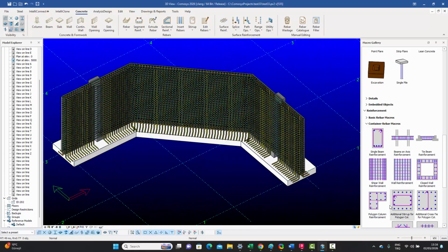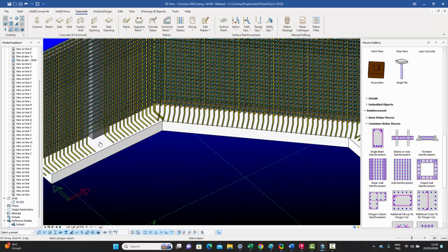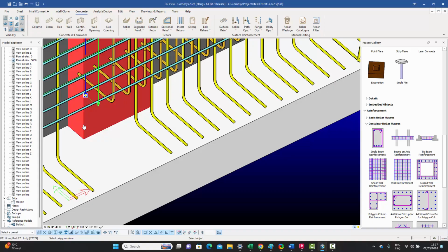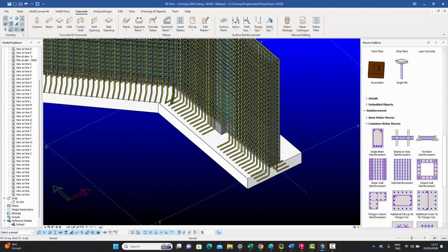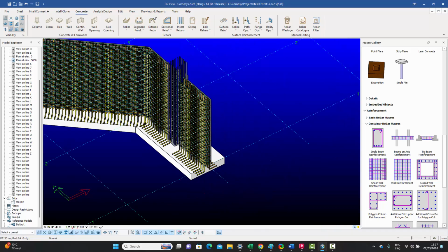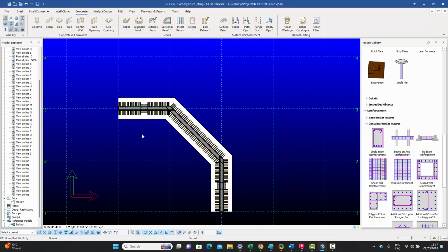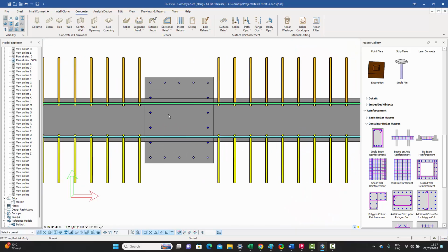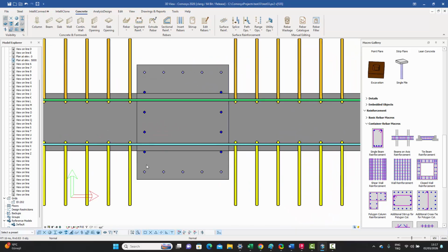So for example, we could go into our polygon reinforcement. This is a topic for another video, but we'll just do it. We'll just select the column, right click, put some reinforcement in there, and select this one, column, and right click, put some reinforcement in there, look at it from the top. So we see that we have our own column reinforcement in that area. So these ones have conformed now to the presence of this particular column, and that's very convenient.